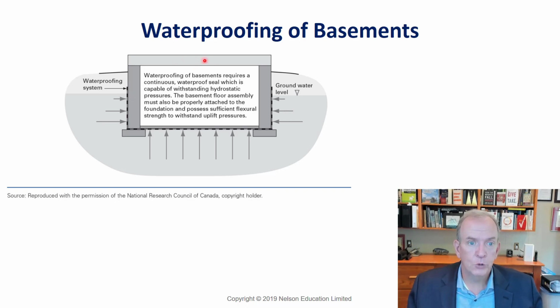And if you don't have the floor joists on the top yet, then it's not laterally supported. And if it's not laterally supported, I've seen where the walls collapse. So you want to make sure that you put plenty of temporary bracing, particularly on long, straight, high foundation walls, because they are what we'd call green, not properly cured yet, because they're very vulnerable.